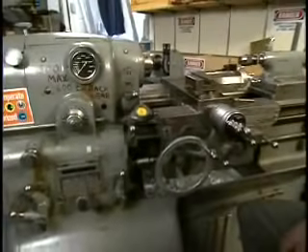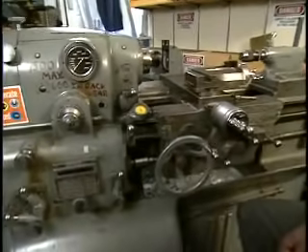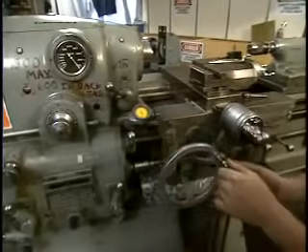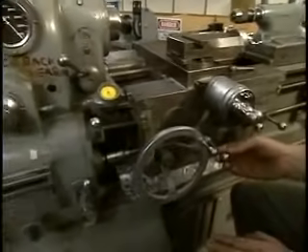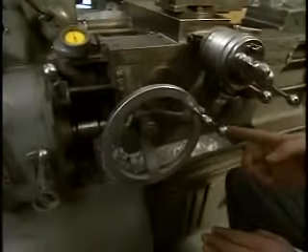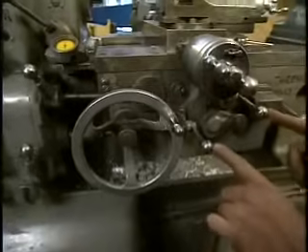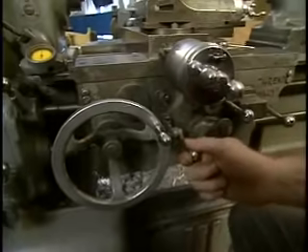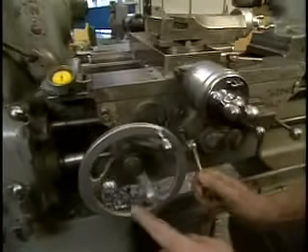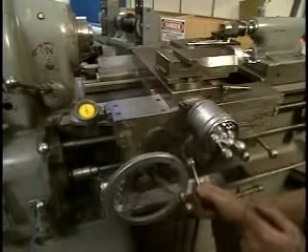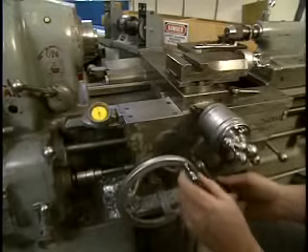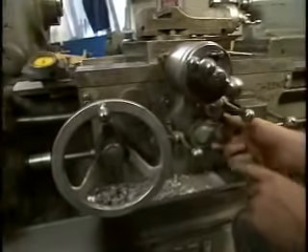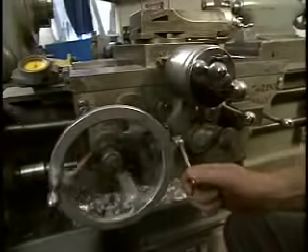All of the axes of the machine can be operated by hand, but for many operations it's desirable to use a power feed. I'll demonstrate that feed now. With the machine on, there is a lever somewhere on the machine. You'll often, on a new machine that you're not familiar with, have to look for this lever. There are no standards really associated with the position of these levers or how they operate. What I'll now do is engage the saddle feed. You can see by the motion of the wheel, the saddle is moving along the bed. Put the lever into neutral. On this particular machine, I have a knob here that allows us to change the direction of the feed.